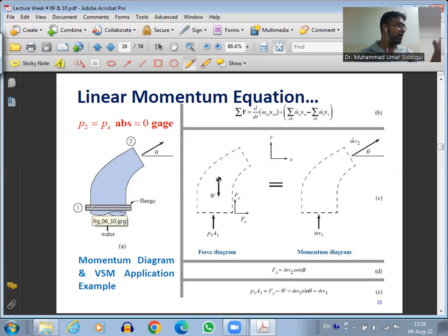And normally, you know that bends are separated from the pipe, and we attach them to the pipe. Now, if the bends are not welded to the pipe, there is another option. We can attach them with the help of flanges. Flanges could be used to attach any bend to the pipe. The flanges are screwed. So we have a flange on the pipe and a flange on the pipe bend, and then the two are brought together, and there are holes. You can just screw them together.